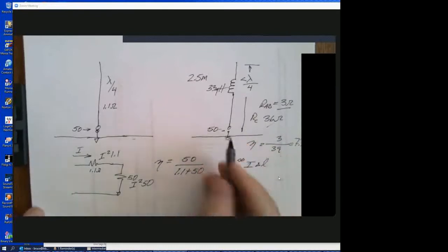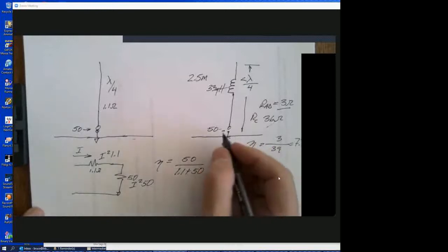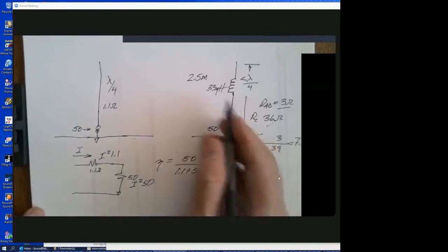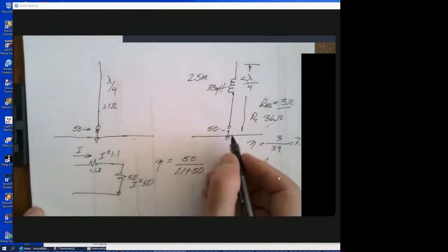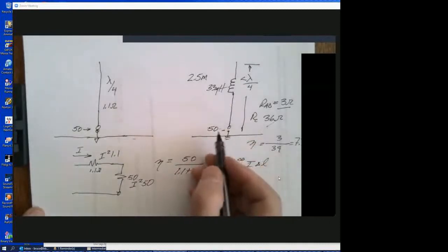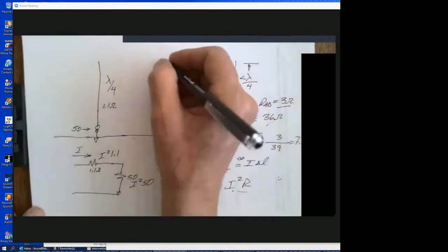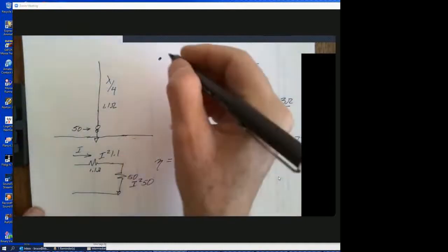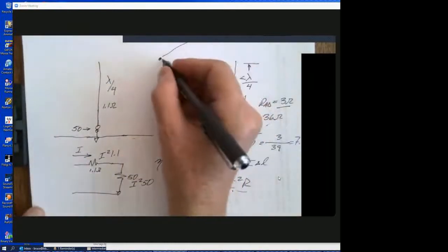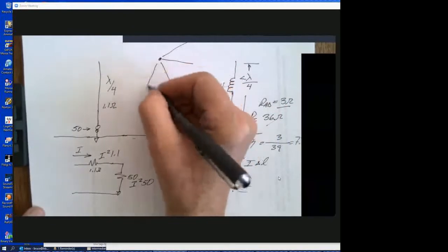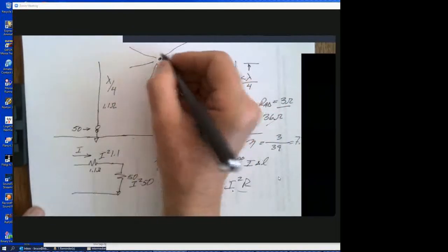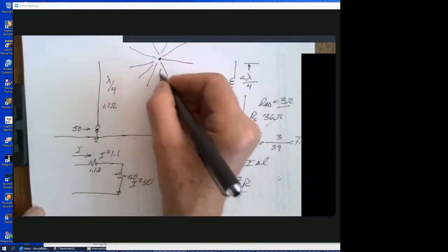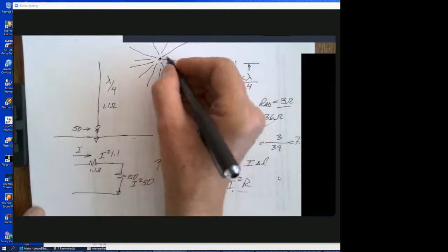That would make this even worse, which is why if you have small antennas, you must have good connections, and why, for example, in the case of a vertical like this, you would want to have radials. Radials are pieces of wire. I'm looking down from the top of the vertical. They are arranged in a star pattern, and you typically want them to be a half wavelength or better, at least a quarter, but a half is good. And you want as many as possible.